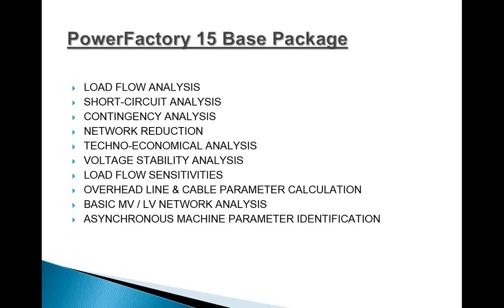Voltage stability analysis we can do. Load flow sensitivity tests we can do in this software. Overhead line and cable parameter calculations can also be done. Basic MV and LV network analysis can also be done. Asynchronous machine parameters, the functions related to the generation part of our power system, can also be analyzed, and the transient cases which we study in our power plant, the generation unit, those kinds of studies can be done in this software. So the base package includes these features.